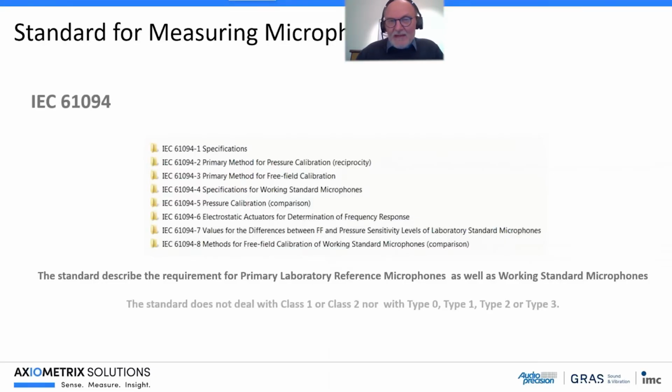Sometimes we hear from you, our customers, that you would like to have a microphone made according to classifications 1 or 2, or type 0, 1, 2, or 3. Actually, the measurement microphone standard does not deal with classifications, classes, or types.